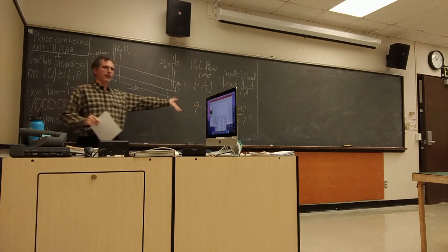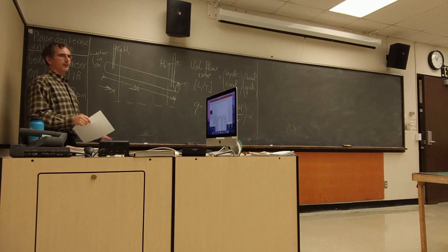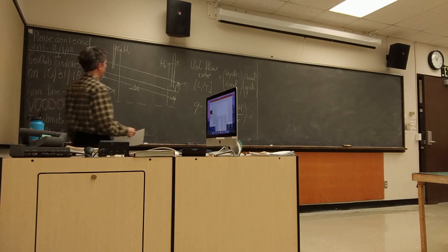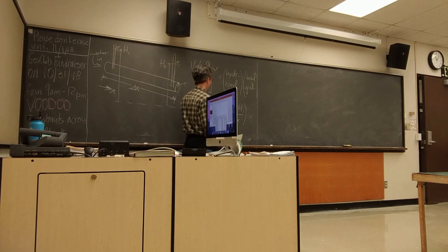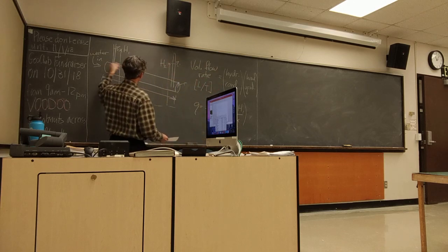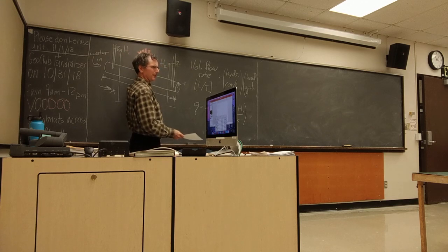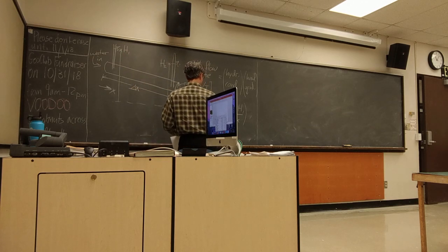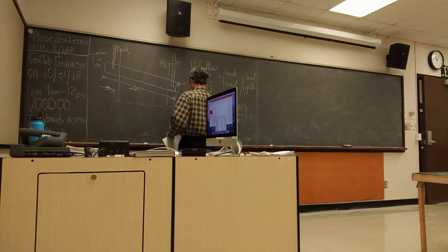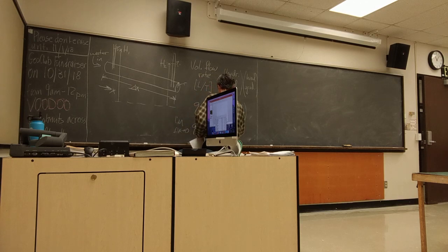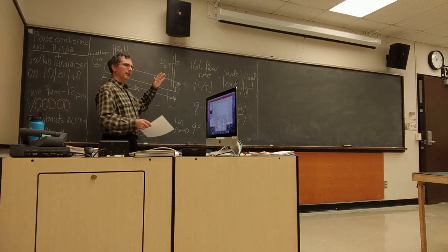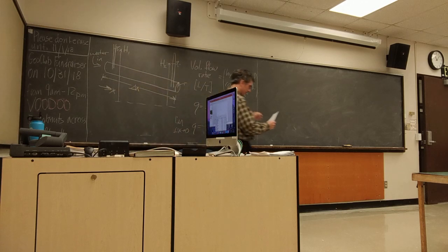If you want to know why I know that I need a negative sign, well, I know that water flows downhill, and so head gradient is going to be defined this way. I know water's flowing this way. The head at 2 is less than at 1. So I hope that's reasonably clear. In the limit as delta x goes to 0, we have Q equal to minus K sat dH dx. All right. So probably you've seen that before, but just in case.